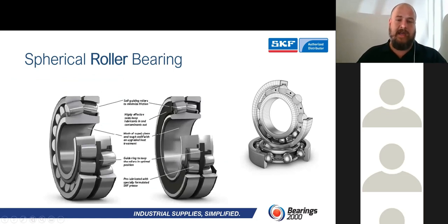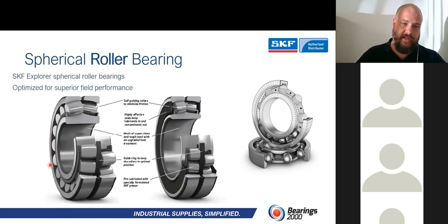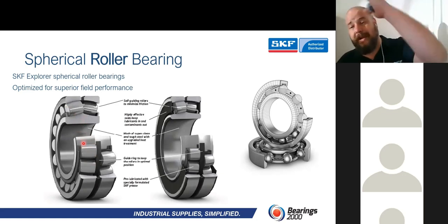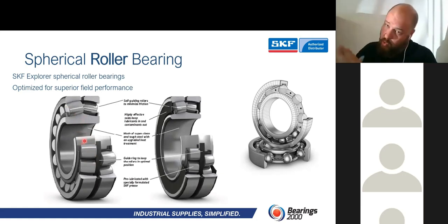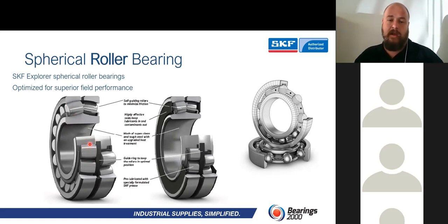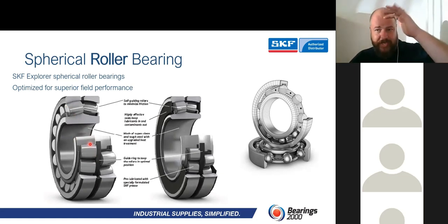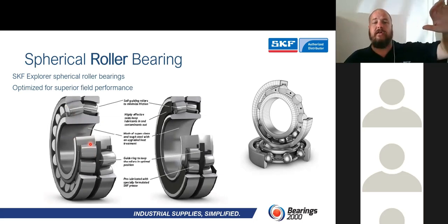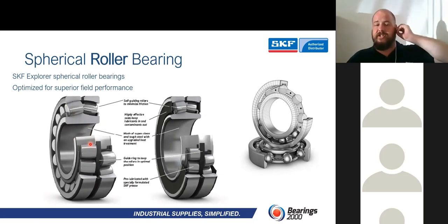As the bearing does come into its loaded zone over here, if it is mounted, if it's hanging an outer raceway, it would be over there. They actually guide these rollers because as a norm, the rollers would come into the loaded state in a vibrationary state and then work their way through the loaded zone. Now they are guiding these with this guide ring, making sure that they come in an optimal position without that excessive vibration coming into that loading zone and causing the damages, right?